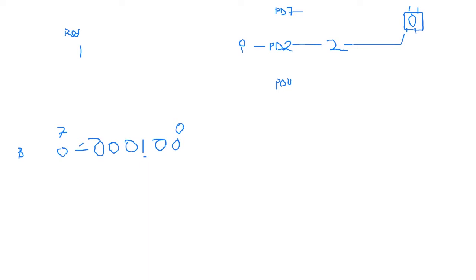So we make sure that at least we create a reference with this particular bit set to 1. How do we do that? Just as we did earlier, we want bit 2, so we shift 1 two times to the left, and everything else will be 0. Okay, all good. We know how to create the reference now.